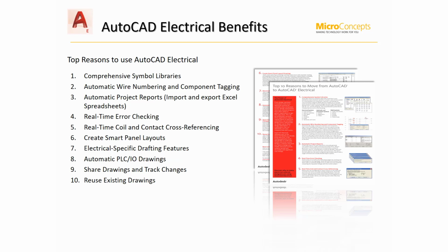As well as schematic design, AutoCAD Electrical is also an excellent panel builder tool. So the panel design can either be driven by your schematic or it could be treated independently as well. As well as the huge component library within AutoCAD Electrical, you've also got electrical specific features which would not be available in AutoCAD or in LT. So you've got different environments within your ribbon, such as schematic, panel, and report environments. The wires as well themselves have intelligence, so you're not just putting down lines as you would inside of AutoCAD or LT.